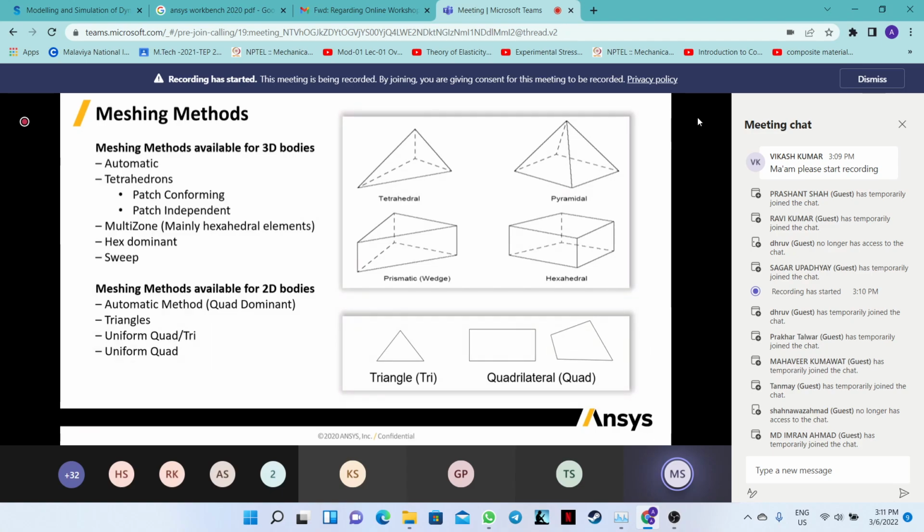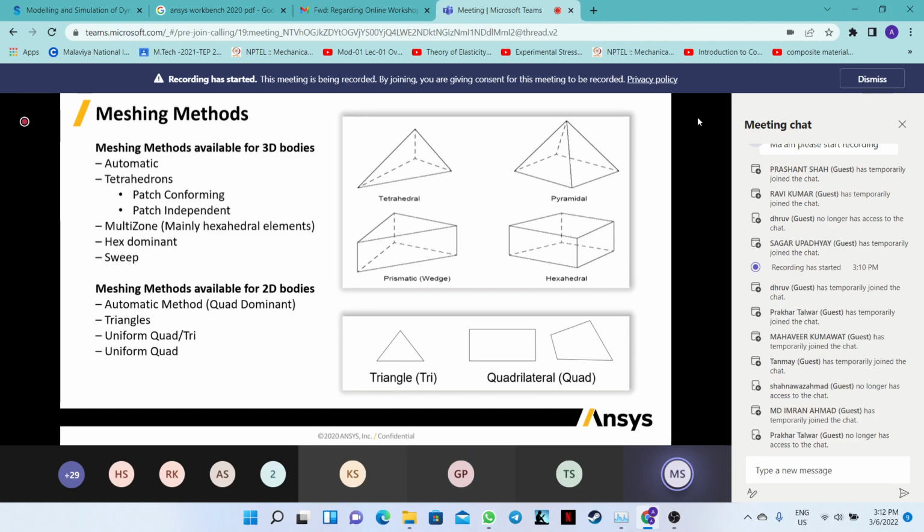Now when you talk about meshing any geometry, the first requirement is that you have a clean geometry. Clean geometry in the sense that if some round features exist at the corners of your geometry and they are not going to play an important role, just remove them. Or clean geometry in the sense that when you import your geometry, there are certain feature losses, and those things you have to cover. Also, there may be too many splits of surfaces; if you convert those into a smooth single surface, you will be able to get a uniform mesh over it. If too many surface splits are there, then definitely there is going to be a lot of headache in terms of getting the quality. So it is always recommended that you have a clean geometry.